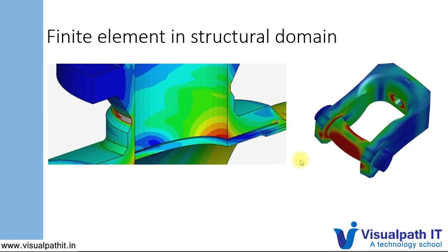It can result in breakdown of the car, and we will not be looking for any such conditions to happen in our real life. So what we will do is model that system using finite element analysis methods, and evaluate the stress, strain, or fatigue life of the component using FEM, and we will be redesigning if it is not able to meet our required load conditions.